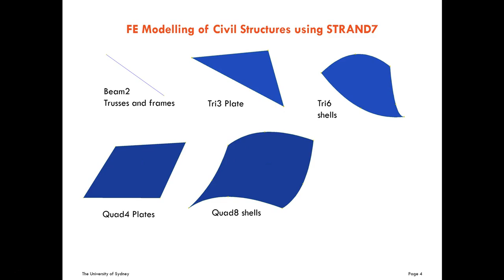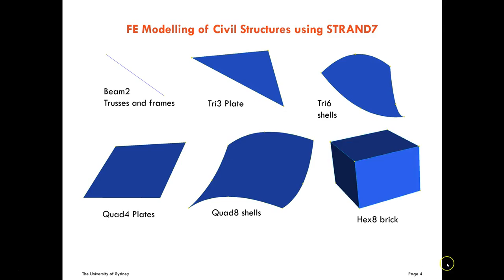So the displacement is a cubic interpolation, so the stress is going to change. The stress is taken from the derivative of the displacement, so it is going to change across the elements. So they are non-constant stress elements, like this one too. So these are the two-dimensional elements, and then we have the brick, like this one, the 8-node brick.